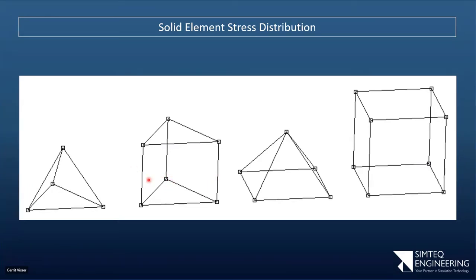On these faces on the outside, though, I can have a gradient. So the stress in that direction, the X direction stress, can vary through the thickness. Same with the Y direction stress, the Y stress can also vary through the thickness. But on the face, if I look at this normal to that face, it's a constant stress in all the directions. This element is slightly worse than this even. It turns out that there's not much advantage in terms of accuracy that we can gain from there to there. So why does this element exist? We'll get to that in the next slide. So just remember this slide.